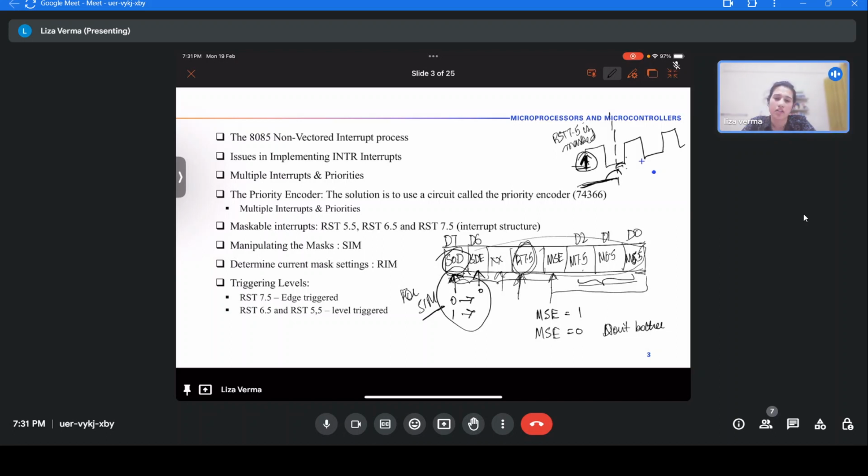SOD won't send anything, no? If SDE is not set, it won't send. The meaning of SDE 1 is that whatever the data or content of SOD is, it will be transmitted. Okay, so if I connect the SOD pin to an oscilloscope and probe the pin, it won't send anything since SDE is what enables the serial data transmission. Okay, so it won't be sending anything.